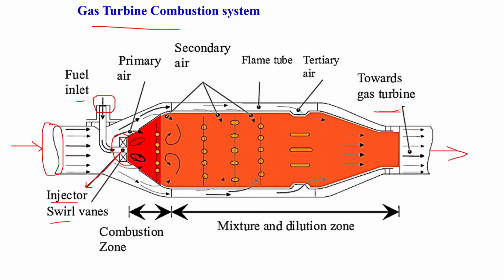Here we need to achieve a certain temperature in order to get the proper thrust for the GT application. We should not get an over temperature than the indicated temperature of the T40. T40 is a very important parameter here.